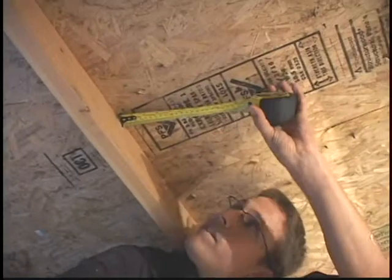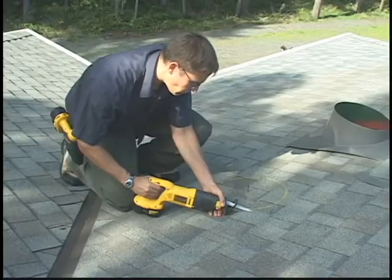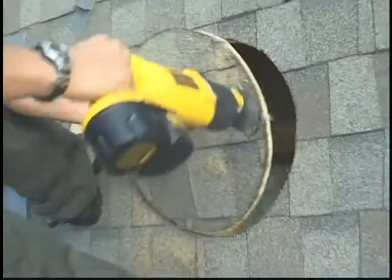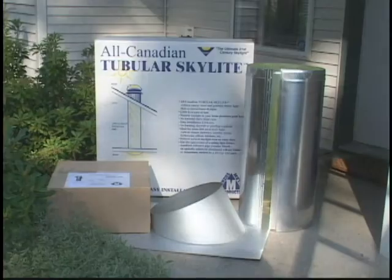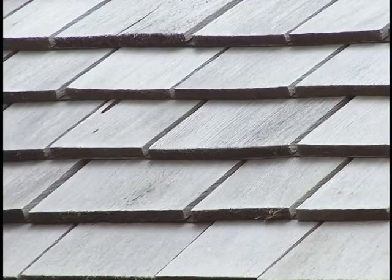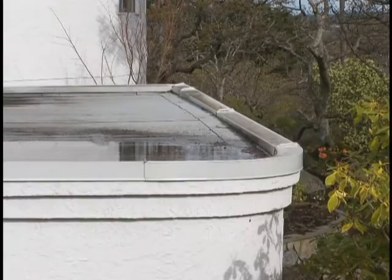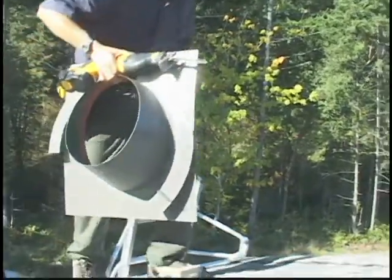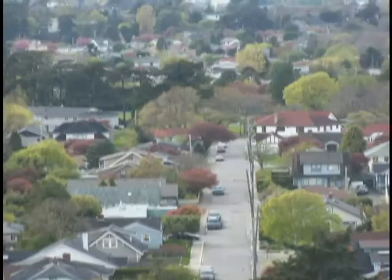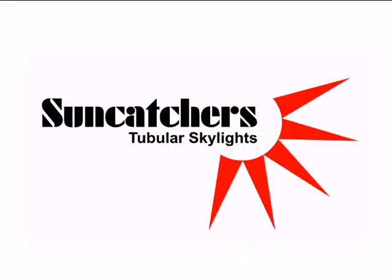This video is designed to help you install your new all-Canadian tubular skylight in a professional and safe manner, whether you are a builder, contractor, or handy homeowner. These instructions will work with most types of shingle roofs. If your roof is tile, metal, or flat, there are other flashing options available. These may require professional assistance, and it's a good idea to check your local safety requirements before starting the installation.